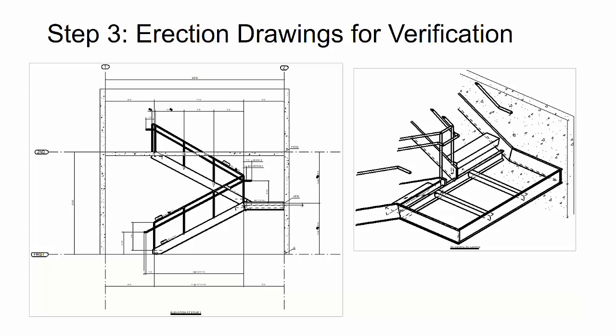Imagine if you didn't have these dimensions or some of these things clarified before you start fully modeling and connecting and detailing everything, and then even making shop drawings. That can be up to 60 or 70% of the cost on your detailing. If you do all of that work and then it comes back that those dimensions change or something needs to be redone, then you have to redetail about 70% of your work, or you're going to be modifying a lot of that and dealing with piece mark changes and chasing through all of the updates everywhere.